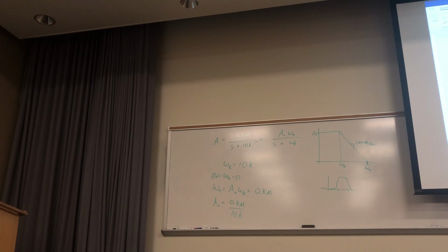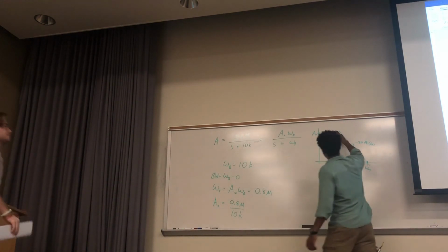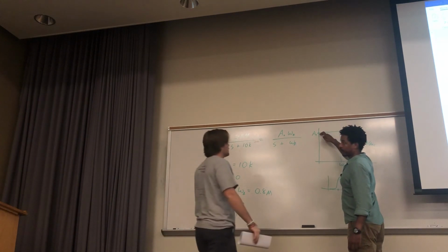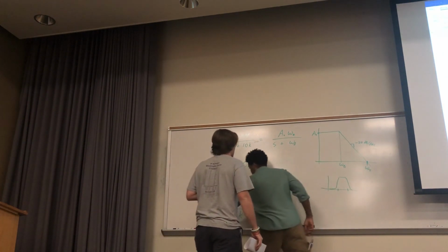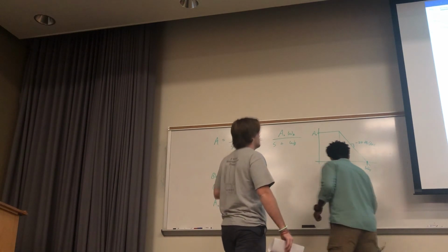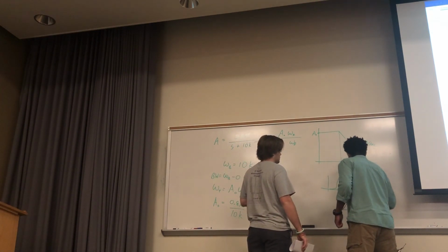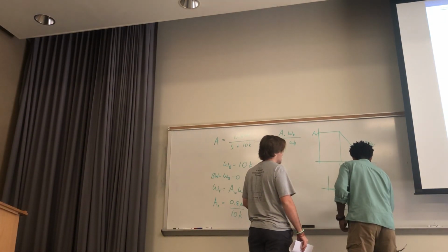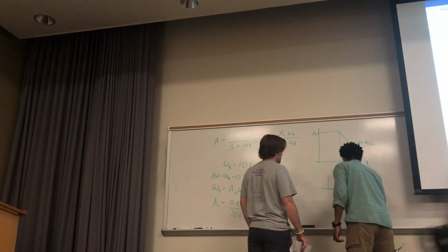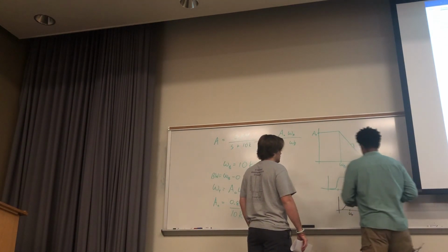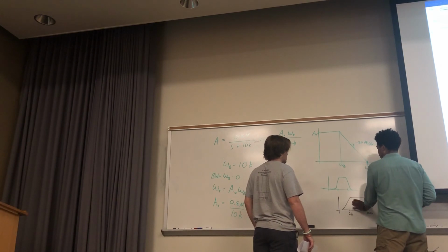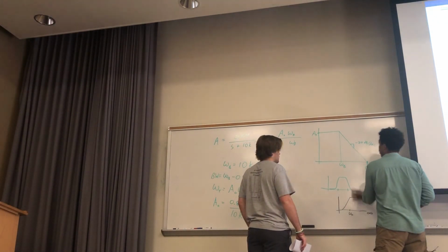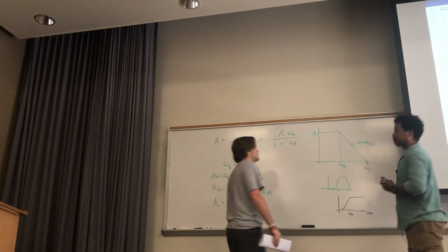Hey, why was that one 0? Oh, yeah, because this piece right here is low pass, so low pass goes all the way over. Now, if it was high pass, that's the opposite, right? If we had a high pass one that went like this, then this has infinite bandwidth, because you got infinity way out here, and then you got this omega h right there. So it's like infinity minus h is the bandwidth. So high pass are infinite bandwidth, but low pass just go to 0. Exactly.